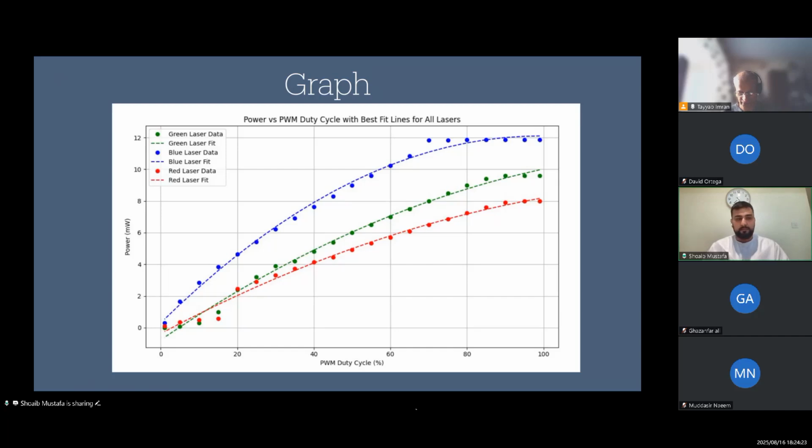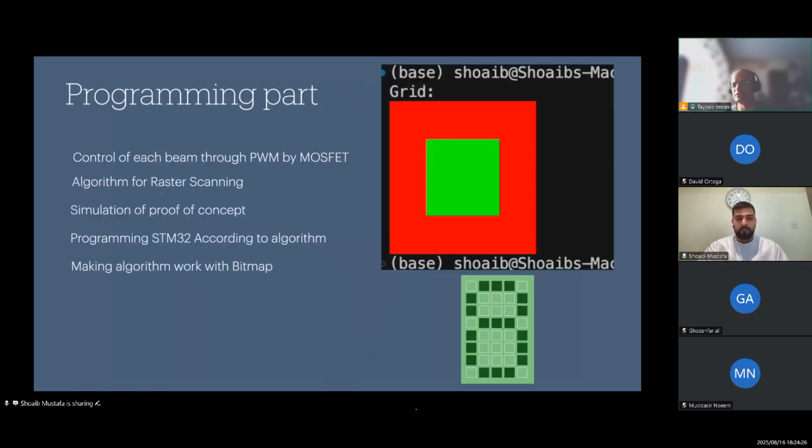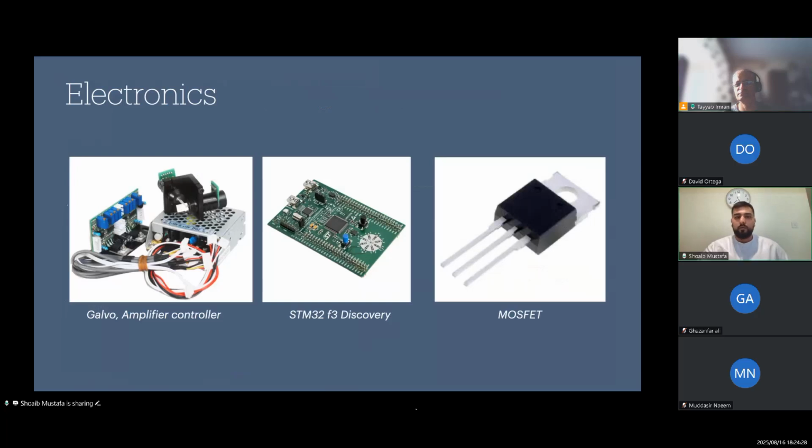And this STM32F3, what exactly is it? Sir, it's a microcontroller on a development board. It gives you the access of programming it through your computer, letting you use the STM32 Cube IDE to use their hardware abstraction layer, which gives you the ability to not write the register level code, but still interface with the peripherals directly, instead of having a framework like Arduino, because that takes a lot of time to compute since it has a lot of checks.